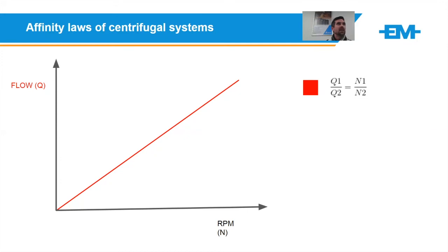So using our part number IFD6500, it's a USB to RS485 converter. The USB plugs into your computer, and the RS485 output will connect to the drive. Then using VFD Soft, you can extract the parameters from that drive and save them in an Excel or CSV format.